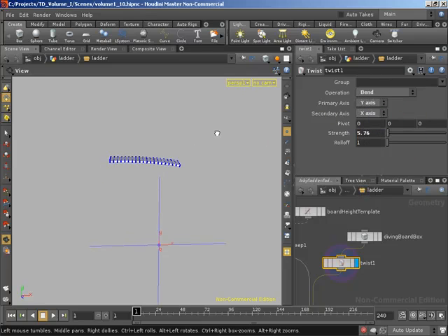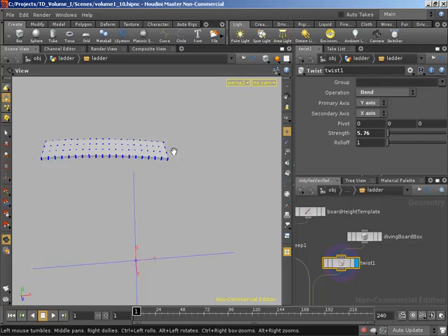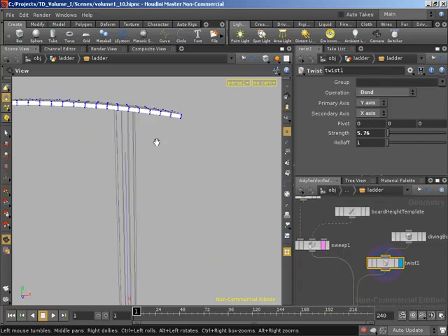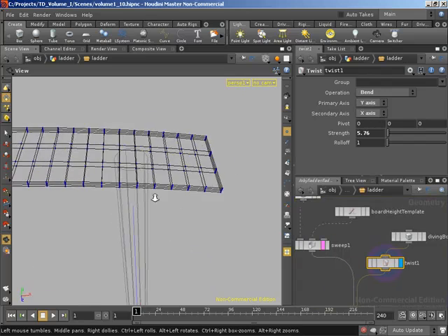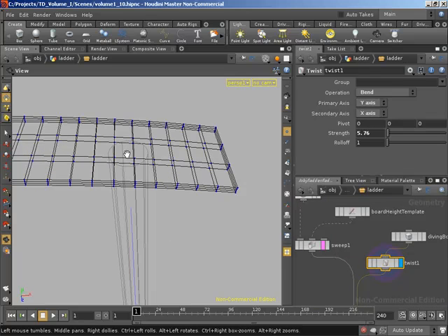So let's alter our pivot so that we bend from the top of our box, basically from the top of our pole. So our pivot in X, I'm going to offset in the positive X direction. Let's bring in our tube. I'm going to offset to this point. We know this to be the origin. If we offset in positive X by the radius of the circle, we'll offset to here.